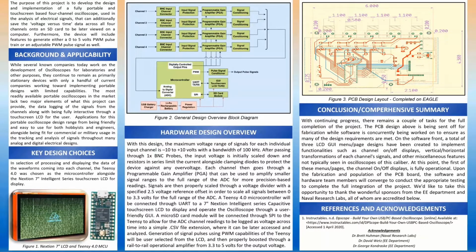A Teensy 4.0 microcontroller will then be connected through UART to a 7-inch Nextion Intelligent Series capacitive touchscreen LCD, which helps to display and operate the oscilloscope through a user-friendly graphic user interface. A micro SD card module will be connected as well through SPI to the Teensy to allow for the ADC channel readings to be logged as a voltage across time reference into a simple CSV file where the user can later access, view, and analyze the data.